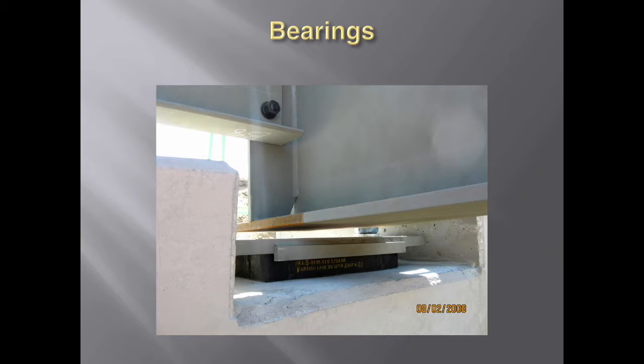There's another issue we deal with. Mark talked about the markings on the bearing pads themselves. Not all the bearings are the same size, and one of the reasons they are marked is so that we can identify where they're supposed to go in the structure. Occasionally, somebody will get busy putting bearings in and not checking where they're supposed to be put, and they'll get put in the wrong place.